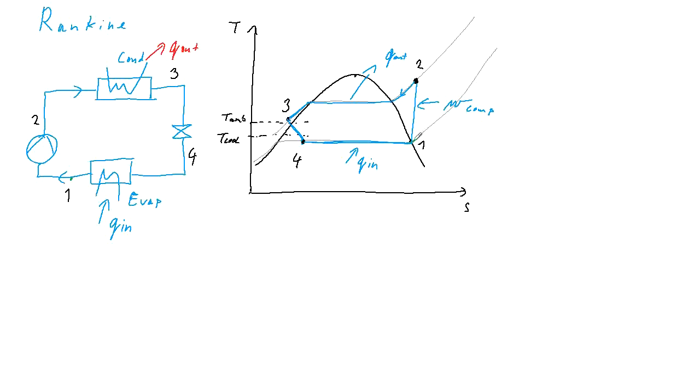It's the safety feature for the compressor, so that it would not get liquid into it, and also it can be caused due to the parasitic heat input in the suction tubing before the compressor. So the point 1 would be at slightly superheated vapor. Then with the real efficiency of the compressor, the entropy would increase during the compression process to the point 3. Then we need to get to the pressure a little bit higher, because there will be some pressure losses.